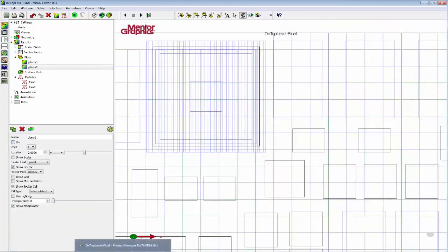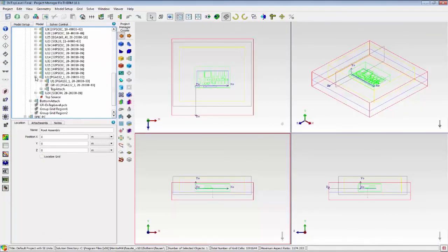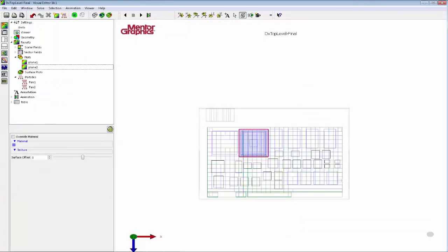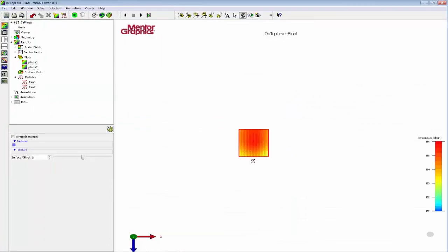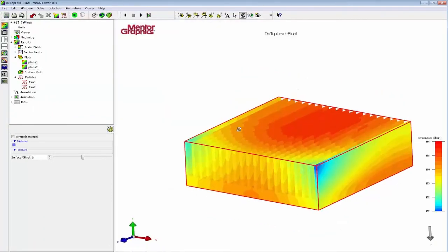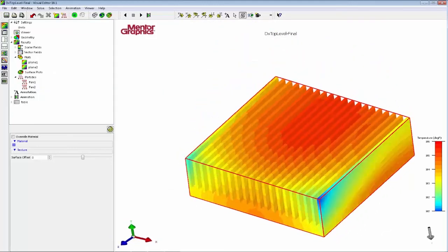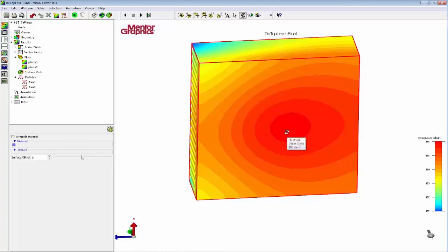What we can do next is something called surface plots. So I'm just going to dig down inside my PCB and find my heatsink, top attach heatsink, heatsink, and I'm going to create, let's view this from the top. So isolate the view, just the heatsink, and I'm going to create a surface plot on here, looking at temperature. So I can visualize what the temperature variation on the heatsink looks like. So you can see I'm getting a range from 186 to 182. And again I can just mouse over and it will tell me what the instantaneous temperature at that location is going to be.